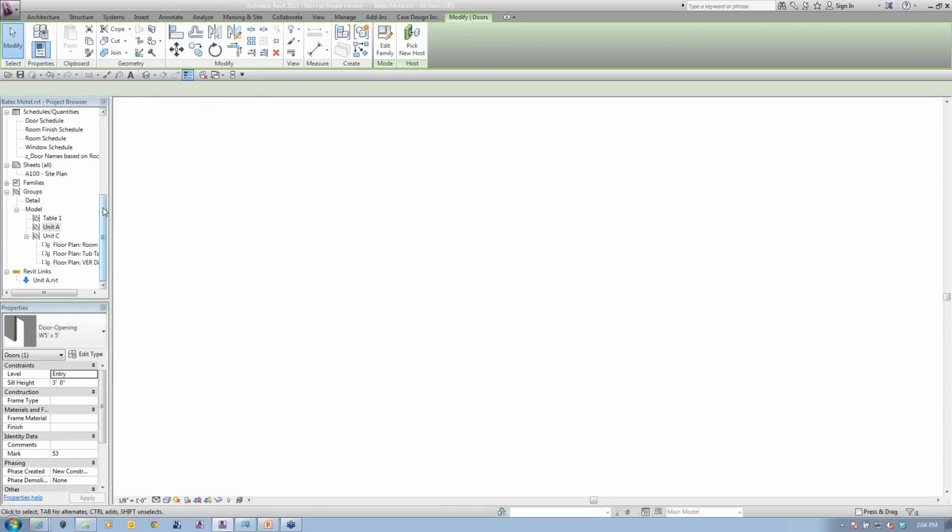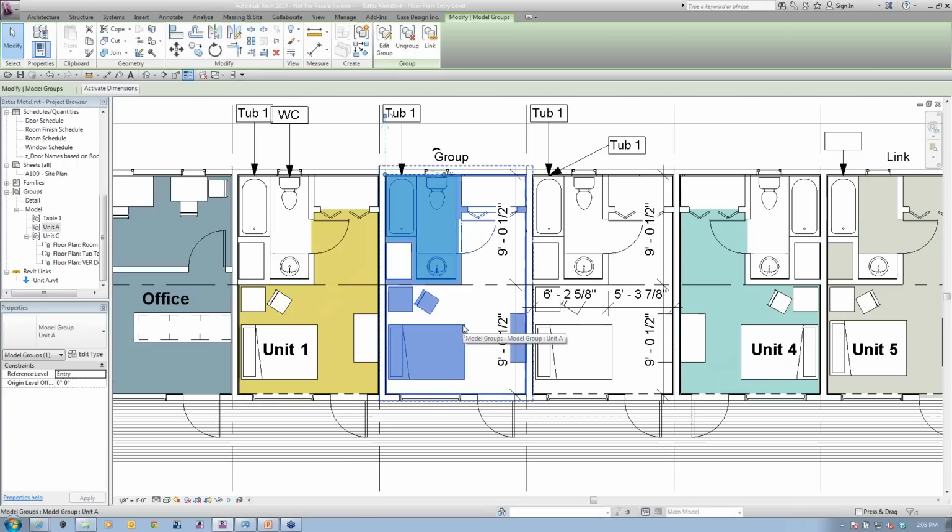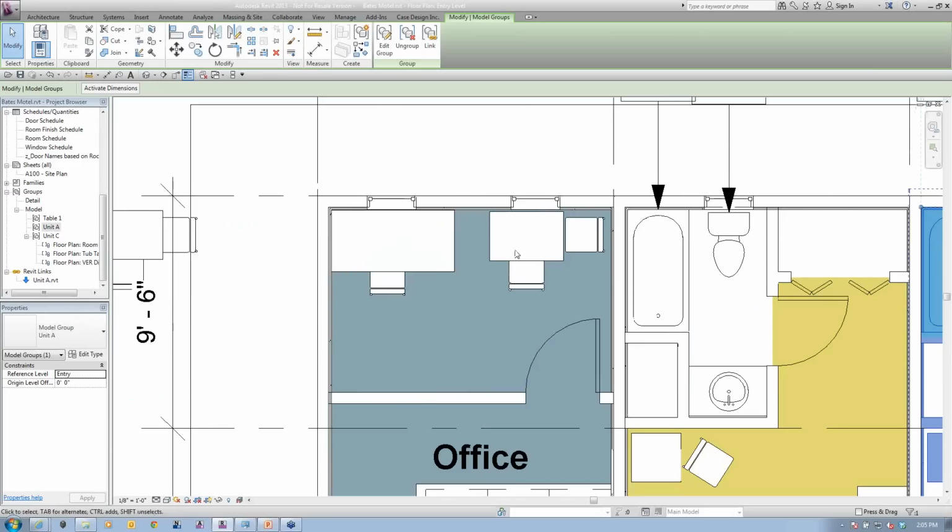All right, so getting back into here, now I'm able to jump back in, and I was going to talk about links. Okay, so further finishing off the group thought, groups basically slow Revit down. Revit is not built to handle groups. So one of the ones that I see commonly is here's a furniture arrangement in here that's a group. It's 2 chairs and a table.